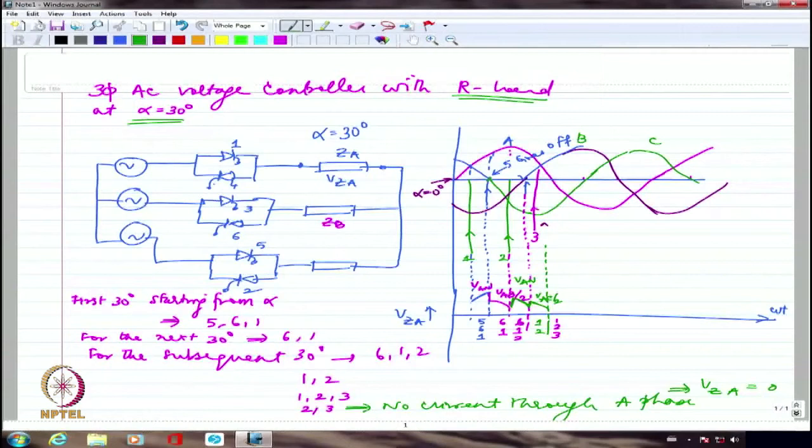So which means the 3-device conduction can extend for longer and longer, depending upon how much is my inductance. But if that continues until the next device is also fired, then always 3 devices will conduct. That's when you won't have any control. All the time per phase voltage is going to come up.